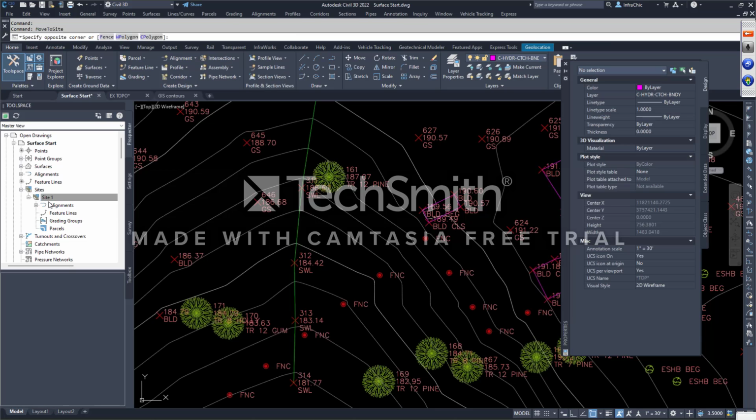When you put feature lines in a site, and there is more than one site, sites do not talk to each other, ever. That's how you separate out the line work. I can put a bunch of feature lines in site 1, and I can make another site, call it materials, and my feature lines will be representations of the exterior edges of, say, gravel, concrete, whatever. And I don't want them to talk to the other feature lines at all. By talk, I mean if they cross another feature line in another site, it will ignore that, like it doesn't even see it. If they share the same site and they cross, they will see each other and marry themselves together, and you will be pulling your hair out.